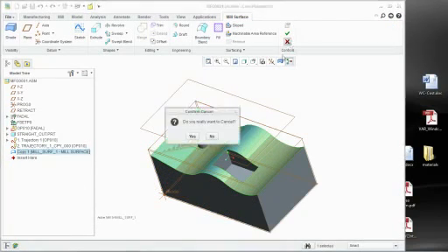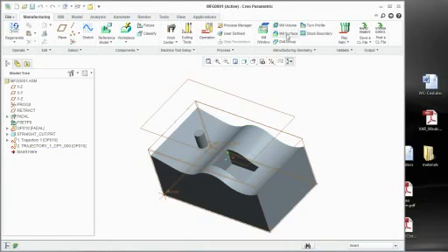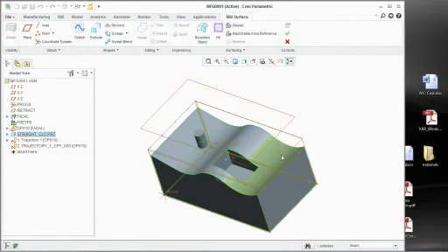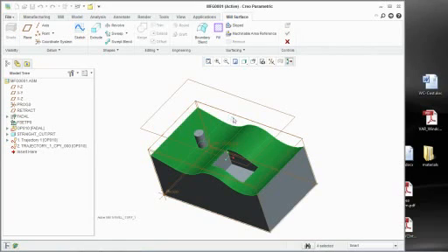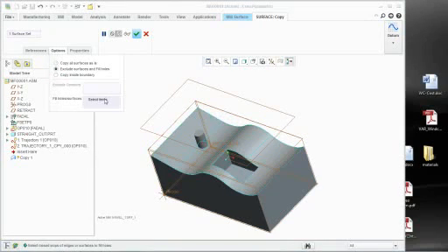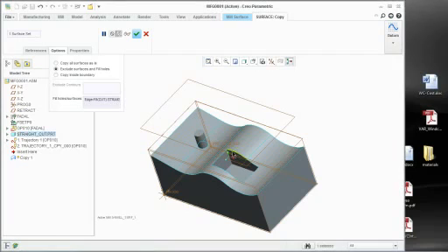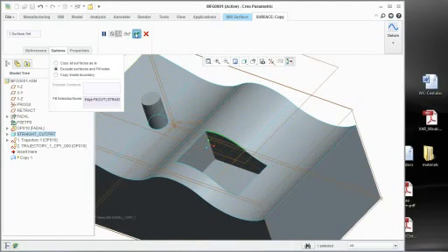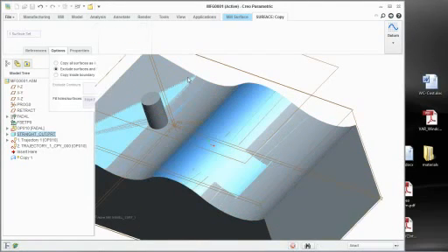One of the things that I have noticed, and if you've never done this before, let's start this all over here real quick, is that if I come in here and create this mill surface, you have these holes, and those do affect the behavior of your toolpaths. If you want to patch holes like this, you can come into the Options tab and notice how it says Exclude Surfaces and Fill Holes. What I can do is pick that, and it says I want to fill holes, and I want to fill this hole, and notice how it fills that hole fairly easily.